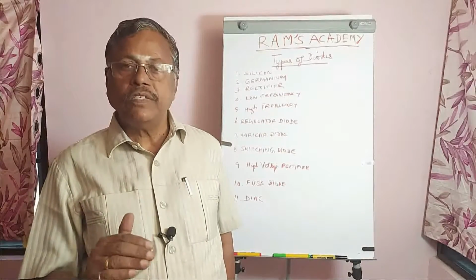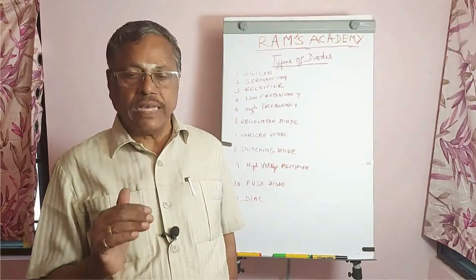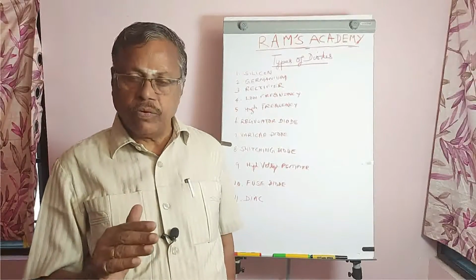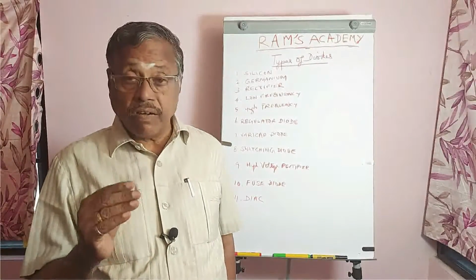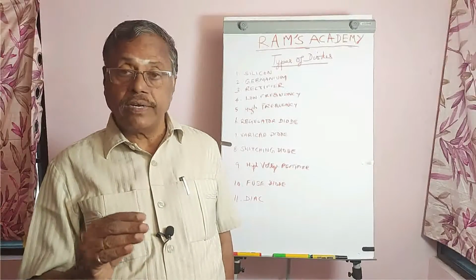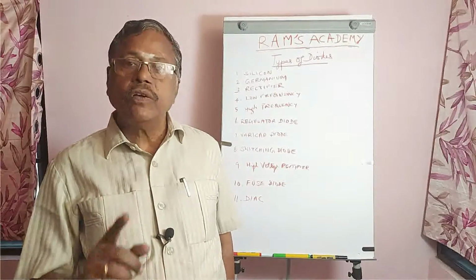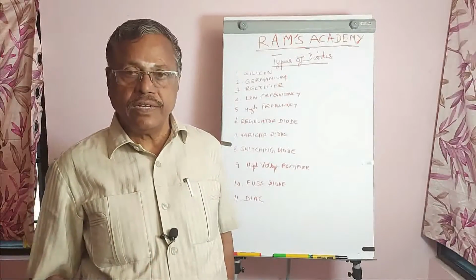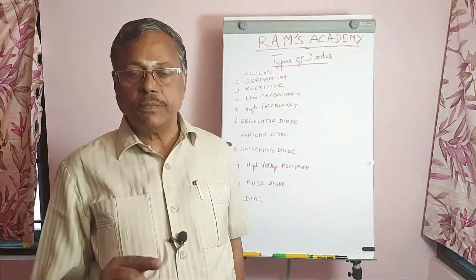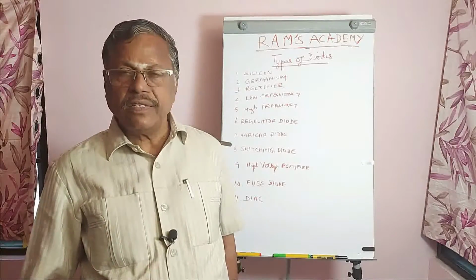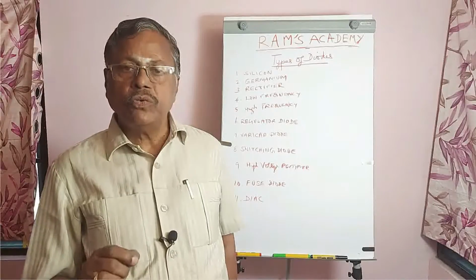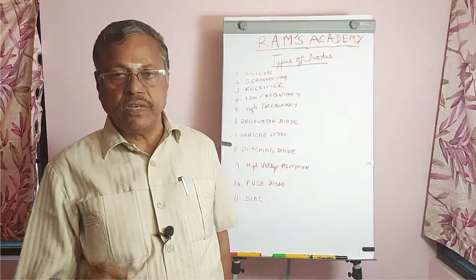The top one, which attracts electrons, is called the anode. Electrons are liberated by the cathode and attracted by the anode, but electrons cannot be liberated by the anode and attracted by the cathode. Therefore, electrons flow in only one direction, not the other. Whenever the anode is positive, it conducts. Because of this property, the vacuum diode could be used as a rectifier diode.